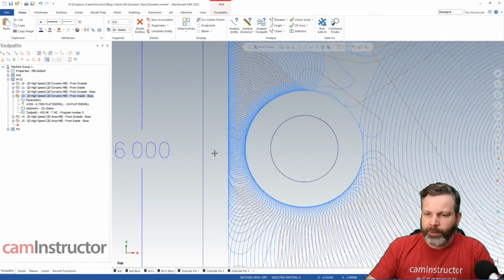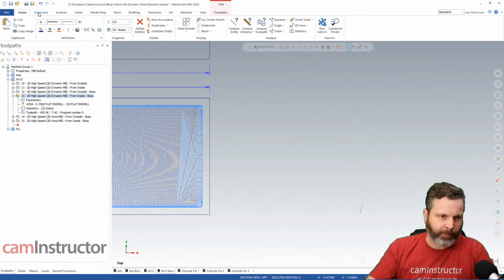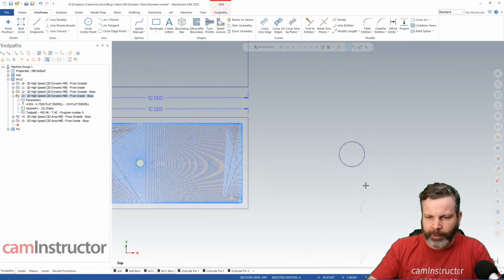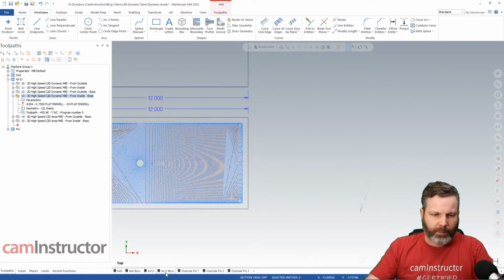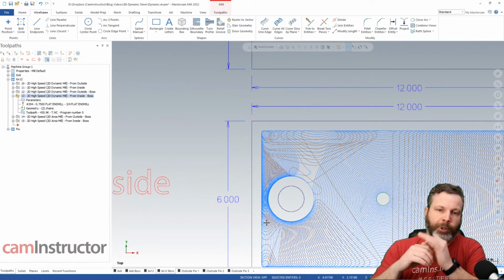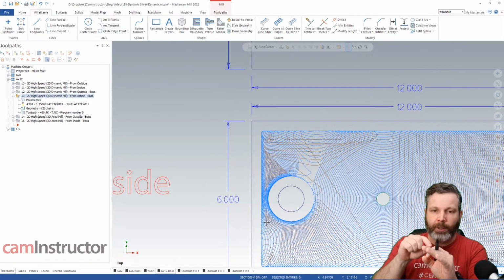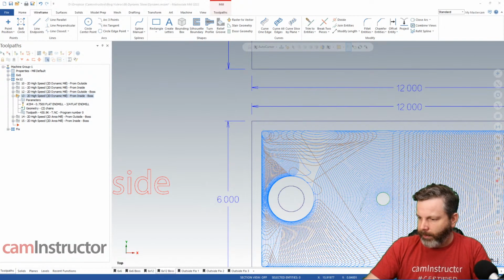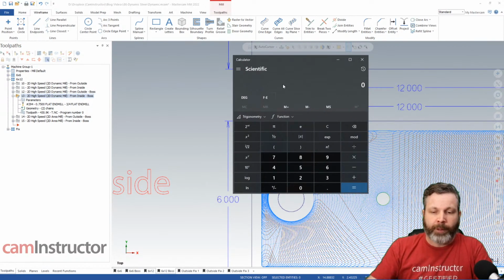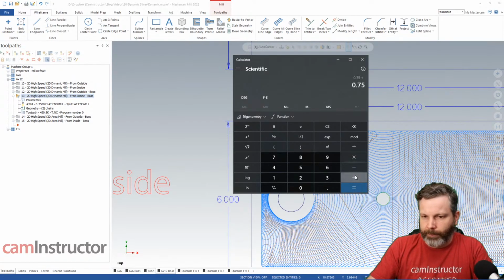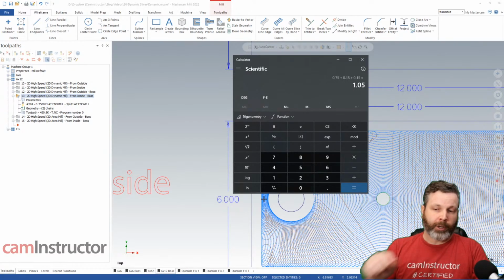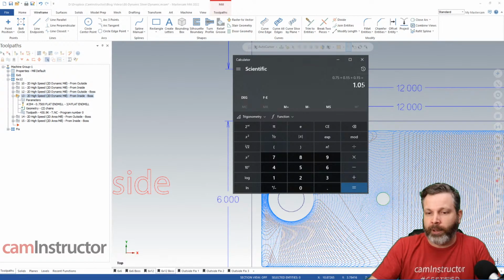Okay. So using that formula they talked about in that video, let me just scroll off to the side over here for a minute. I guess you don't really need to draw this stuff. I can just explain this with math. So basically, if we have a 3/4 inch cutter and we're making a .150 radius, we're programming the center of that cutter and we're making a circle that has a radius of .150. Let me bring up my calculator here. To figure out the diameter of the hole that tool is actually cutting, we take the diameter of our cutter, .750, and we add that radius of the tool path to it twice: plus .150, plus .150. So in that section of tool path right there, we're cutting a circle that is a diameter of 1 inch 50 thou.